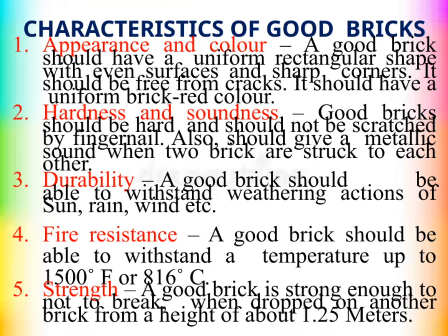When assessing the appearance and color of a good brick, look for a uniform rectangular shape with smooth surfaces and sharp corners. It should be free from cracks or any visible damage, and the color should be consistently brick red throughout. These visual cues indicate quality and proper manufacturing.